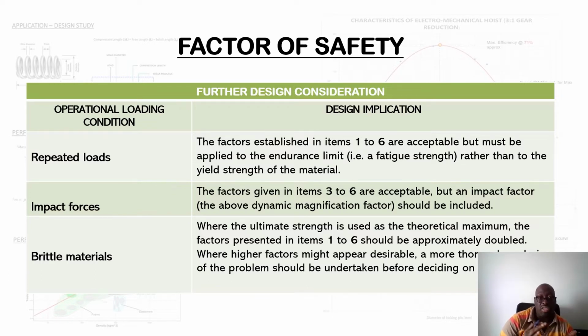So you need to think about whether you double the safety factor. On the previous page we looked at typical values of 3, but for a dynamic loading situation, maybe that needs to be doubled or tripled, depending on the material.